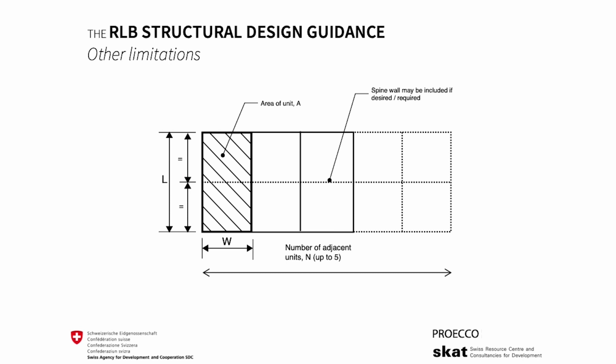The design tool provided has been developed to facilitate the design of relatively simple buildings, with an arrangement based on what may be expected of terrace low-rise affordable housing. In order to reduce complexity, the design tool has been developed with certain limitations, like a maximum of 3 stories, the shape of the building, and the design of single units with floor and roof structures spanning across the shorter direction.